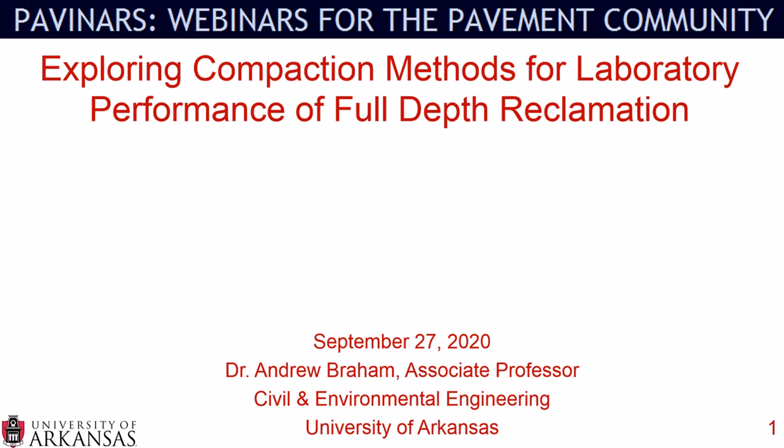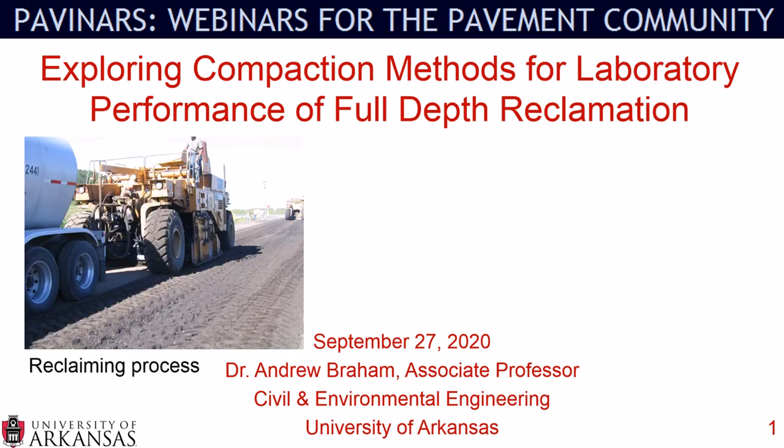My name is Andrew Braham, and today we'll talk about exploring compaction methods for laboratory performance of full depth reclamation. On the left here, you can see a full depth reclamation treatment being placed in the field. You have the reclaiming unit in the center. Some sort of stabilizing agent is being added to the FDR process, and you are reclaiming a certain depth of both bound asphalt concrete and unbound either aggregate base or natural soil.